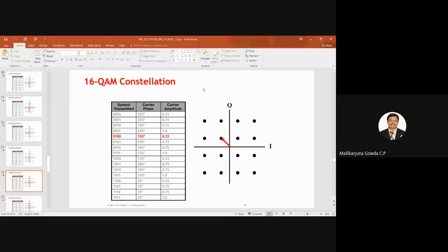Since I'm saying counterclockwise now, the next quadrant is the third one. So change in amplitude and phase, right? For every one of these. Accordingly, if you look at this, you will be able to see there is only one bit change from one code word to another code word. Just have a look. First four zeros are there, then from this four zeros to this one, only one bit is changed, right? That is, the first bit is changed from 0 to 1. Next, with respect to this code word, there is one bit change.